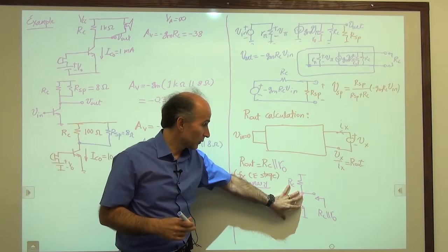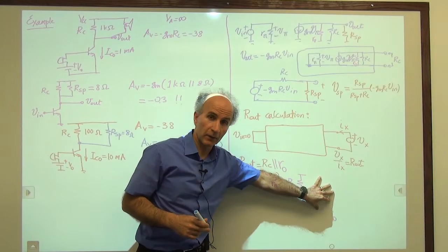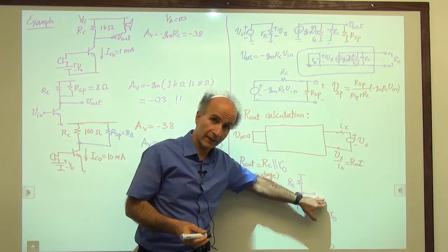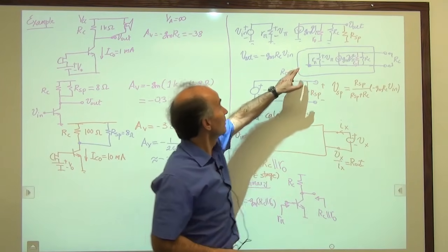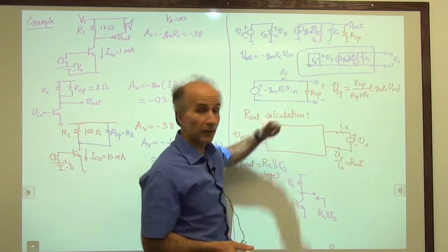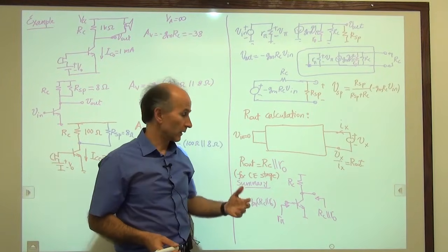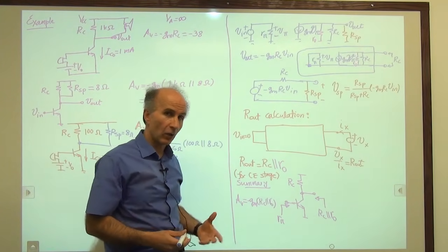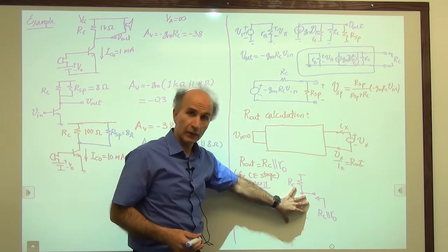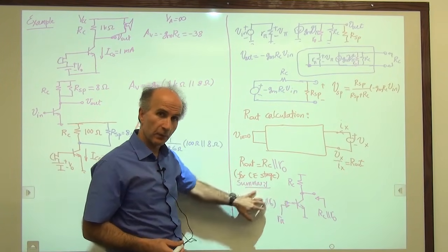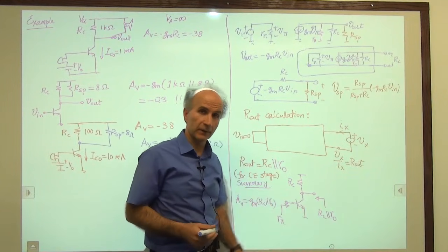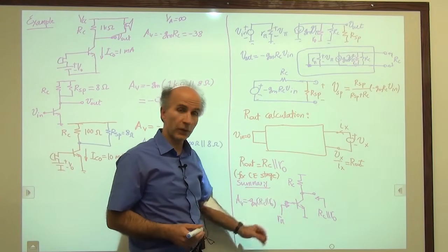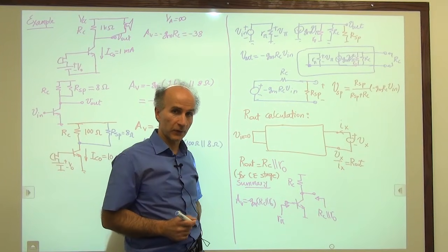When we connect this to the speaker, to drive a speaker, and the speaker has a low resistance, then we have attenuation at the output, as we remember from this structure here. So the input and output impedances play a role in how this stage interacts with other circuits before it and after it. And that's a relatively complete picture of the behavior of this circuit.